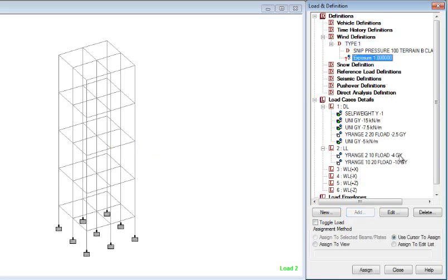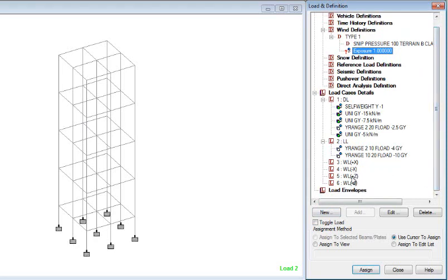Now we have got the exposures, and this exposure is use cursor to assign. This exposure acts on different portions. Say the exposure acts as 1, meaning the pressure that has been generated can act on this place, this place, this place, in X plus X, minus X. X plus is in this direction and X minus is in this direction, so the wind flows in four directions.